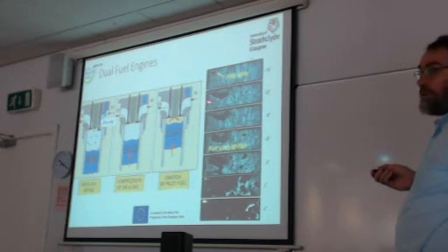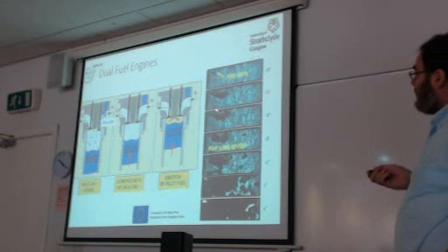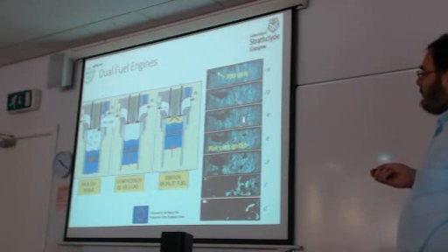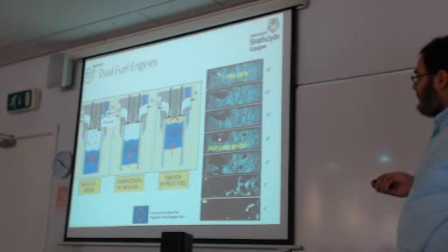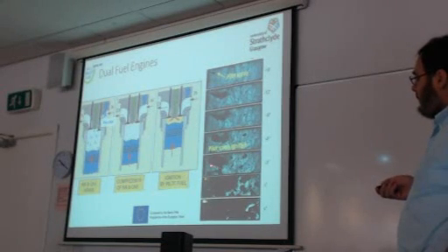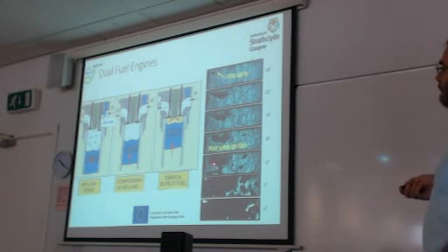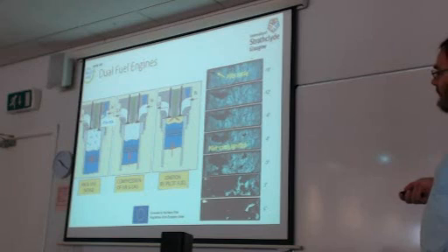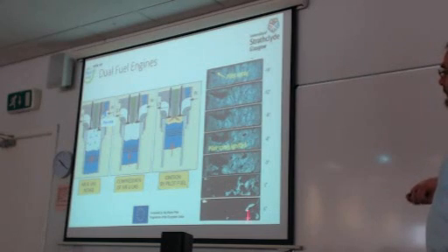And let's see in these frames what happens or how combustion starts. So we have the pilot spray, the development of the pilot spray. As I mentioned, the spray breaks into small drops, and the small drops break into smaller drops, and there's a mixing between the drops and the mixture of gas and air contained in the combustion chamber. And somehow and somewhere, the pilot spray will be ignited. This is the area where we have the start of the ignition, and this will provide the energy to burn the whole mixture contained in the combustion chamber.